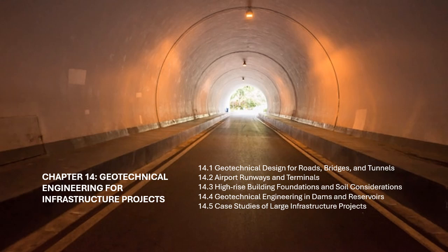Subgrade evaluation. One of the primary geotechnical considerations in road construction is the evaluation of the subgrade soil. The subgrade must have adequate strength and low compressibility to prevent excessive settlement and deformation under vehicle loads. Engineers assess the subgrade soil through laboratory tests, field tests, e.g., standard penetration tests, and site-specific investigations to determine its shear strength, compaction characteristics, and load-bearing capacity.